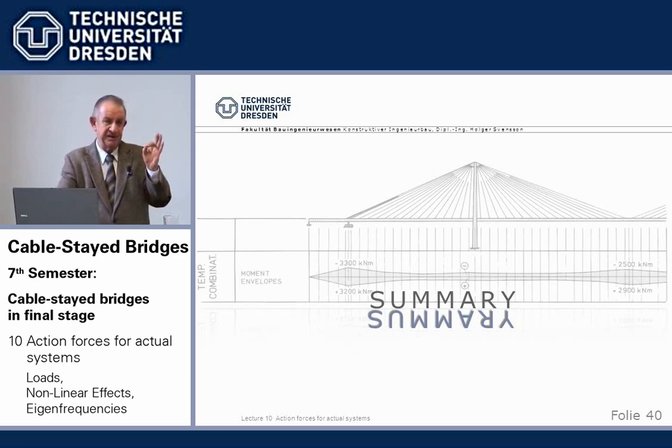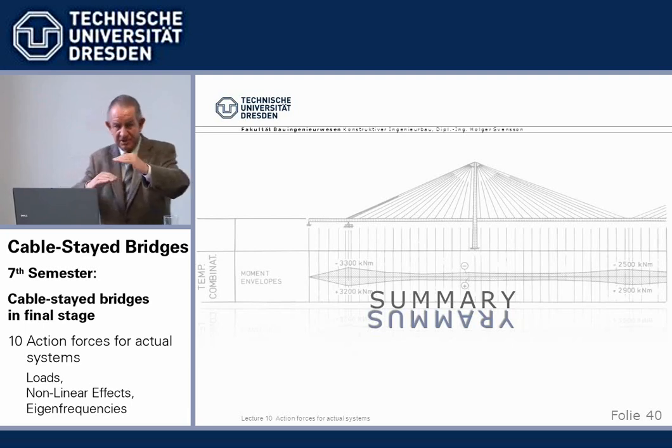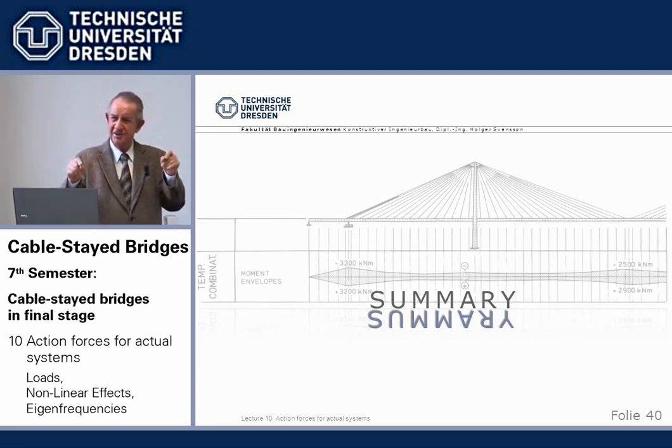But what I insist is that you understand the flow of forces. And for example, this increase of second order beam moments in connection with the depths, because that goes in the very first try of the design when you say, what depths, let's make it slender.